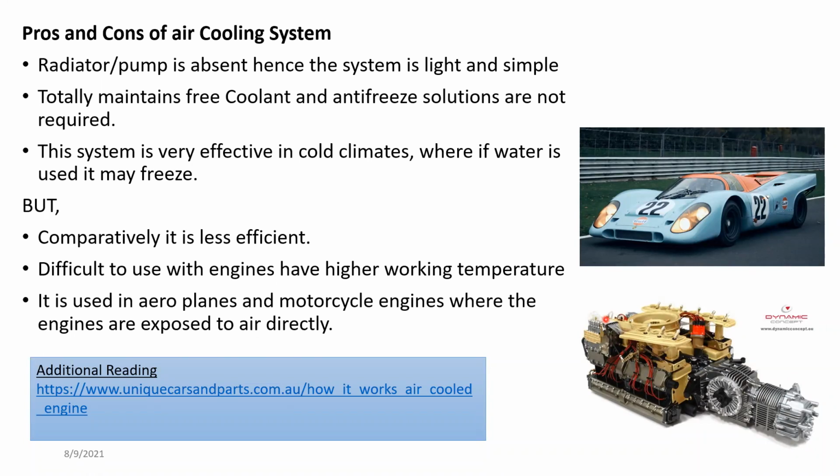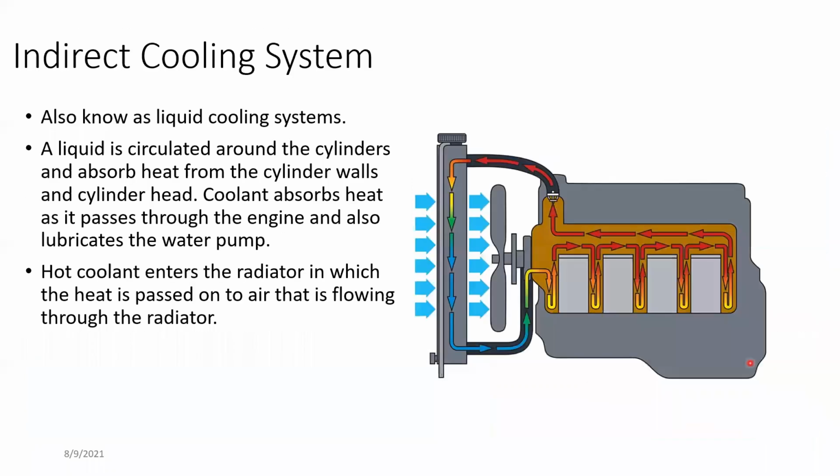Because of this system, they were able to develop even better models, and it was used until 2000 or so. Especially with the strict emission regulations, the cooling of the engine became a very big issue. That's one of the main reasons this particular manufacturer switched from air cooled to liquid cooled engines. So at the moment no one is manufacturing air cooled production vehicles.